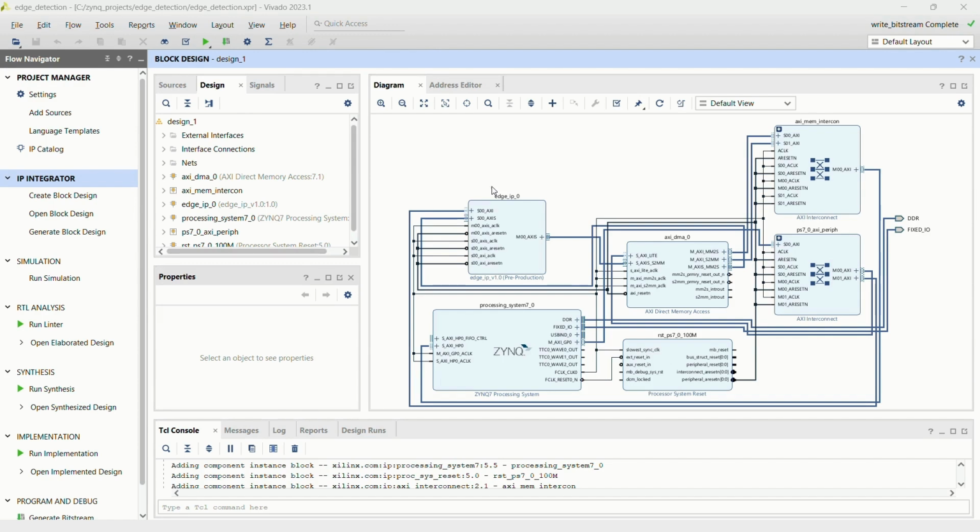As you can see, I have added a custom module, where the wizard auto-generated a Verilog file with 3 AXI interfaces: an AXI Lite slave for control registers, which we left unchanged, an AXI Stream slave to receive the incoming data, and an AXI Stream master to send the processed image. In this project, we will use this as our main module, where we will write the Sobel algorithm